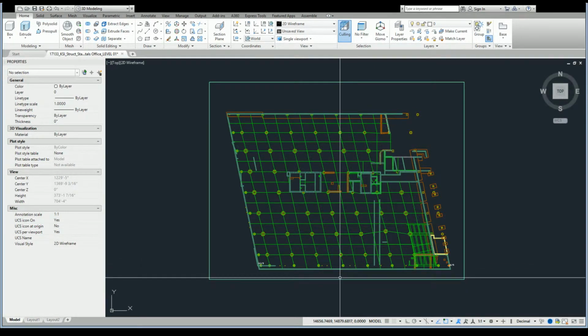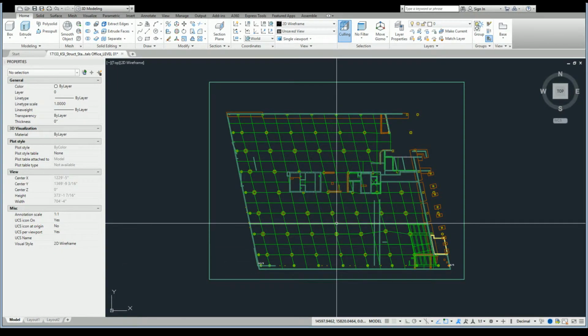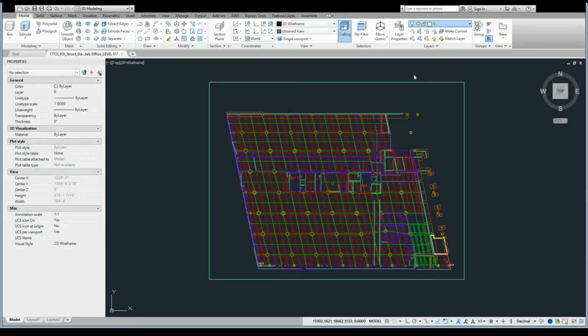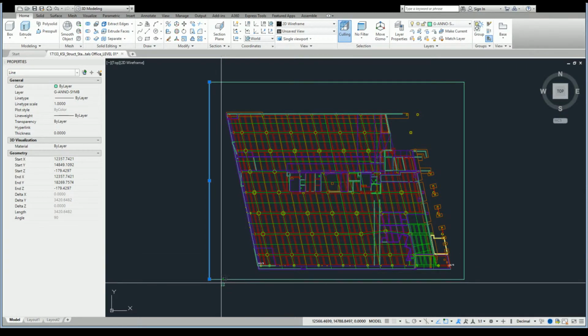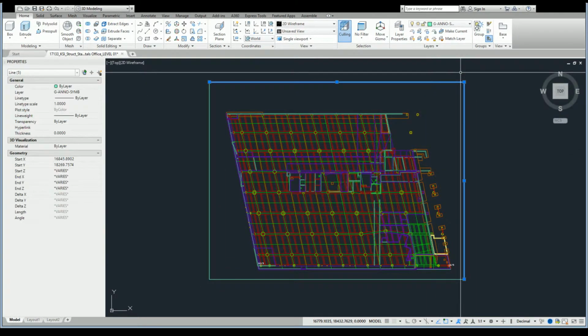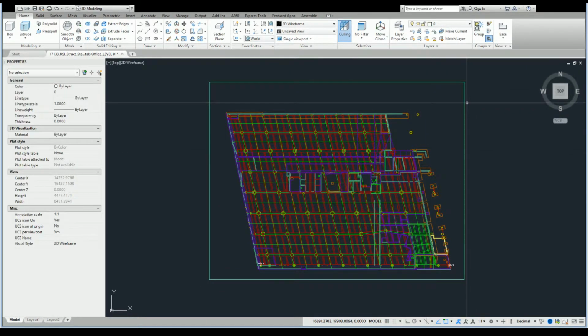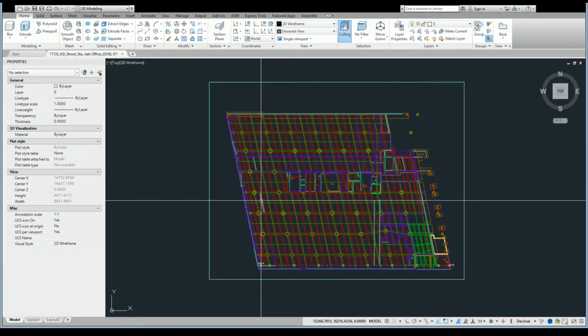So first thing I'm going to do is switch it over to decimal feet, and now my coordinates are good, decimal feet wise. And the other thing I want to do before I move anything is turn all my layers on, because I don't want any layers to stay where they are. So turn all my layers on here. Sometimes I might clean this stuff up just to get rid of it, but since it's not my drawing, I won't do that.